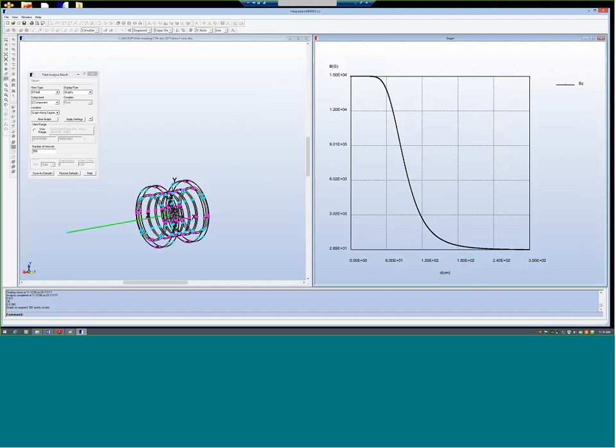And at 3 meters away from this coil you got something like 28.9 Gauss. Let's take 30 Gauss. At this place you got 30 Gauss. Now, in MRI applications, these high magnetic fields are shielded with a metal box around them. So we will go to the shielding part now.